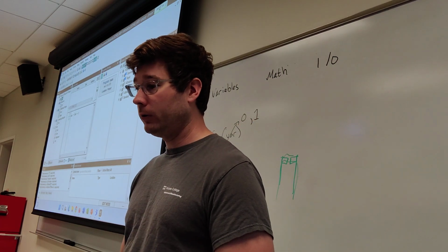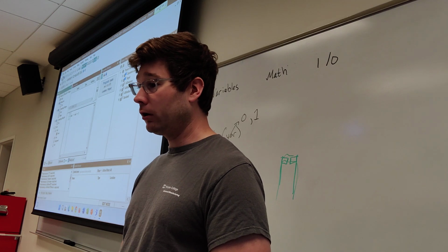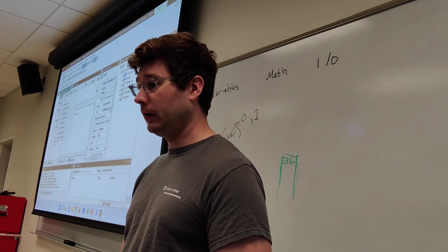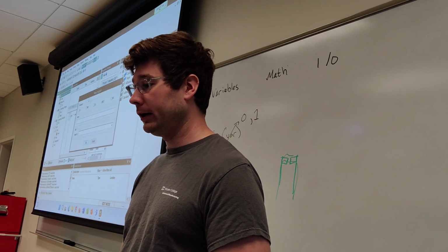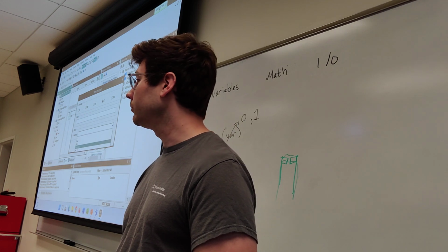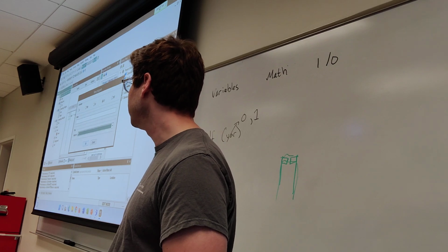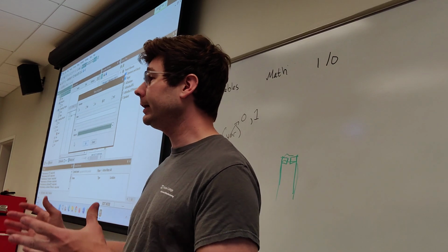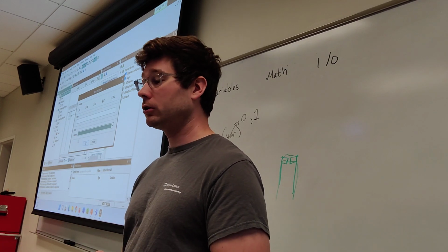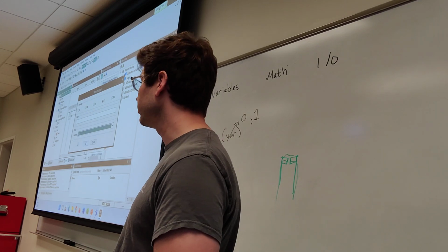So whenever we have programs that we need to run, we need to drag them, or upon creation, when we're adding new programs, we assign them to a group right at the start. Okay, by default, be careful, it doesn't assign it to a group. You could easily have it not running at all. Make sure you put it in the appropriate fast, slow, background or init group, usually fast.